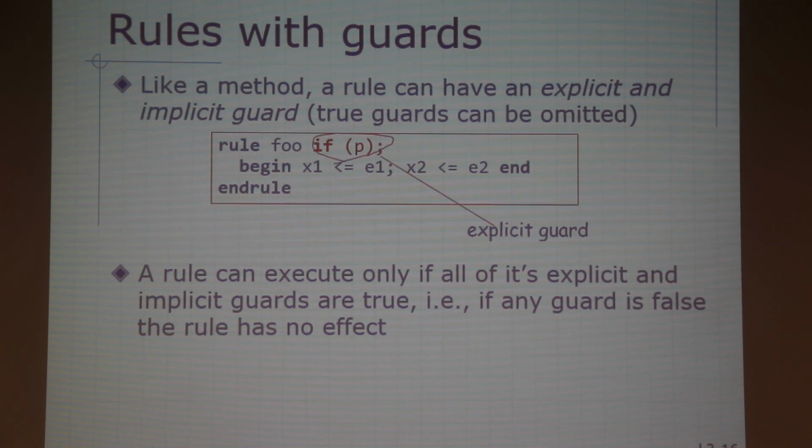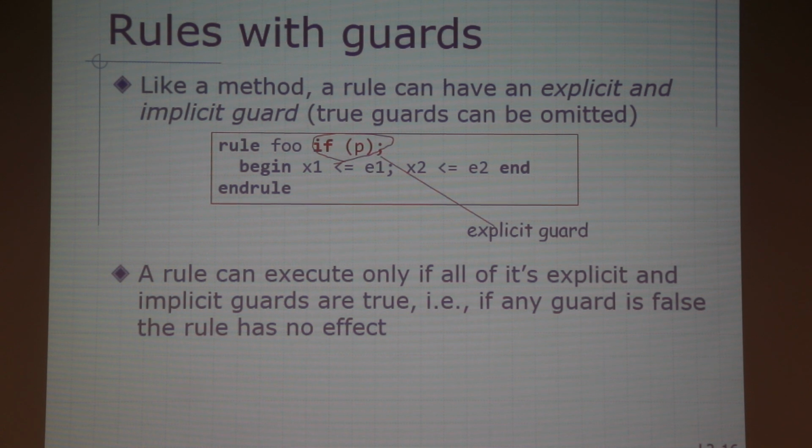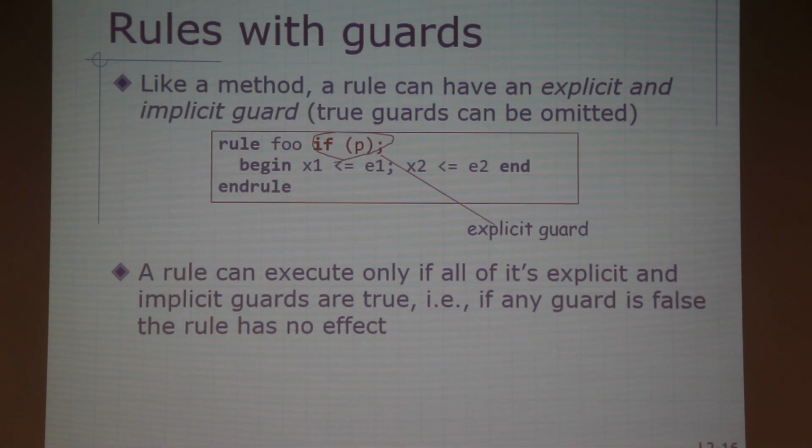You say this is an edge trigger semantic, so that if one of the P's transitions from 0 to 1, execute. No. You should think of any signal in this system as if you're reading some register. So P either is directly coming from a register or you're applying some combinational function to a register. It's a level kind of signal.